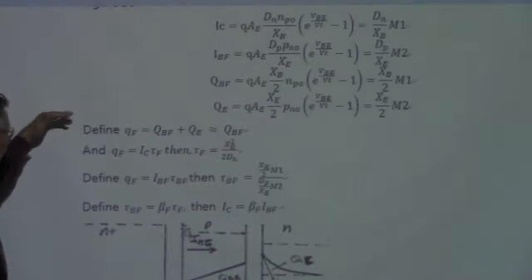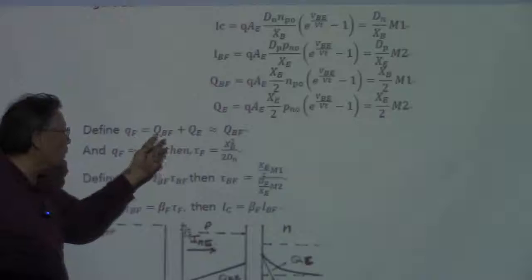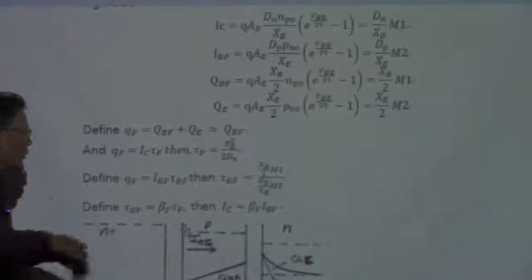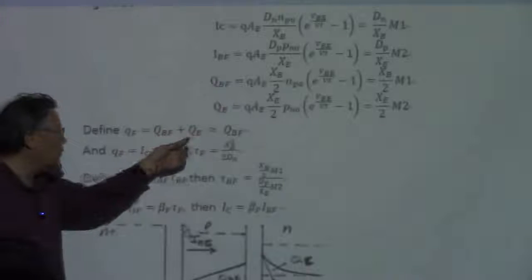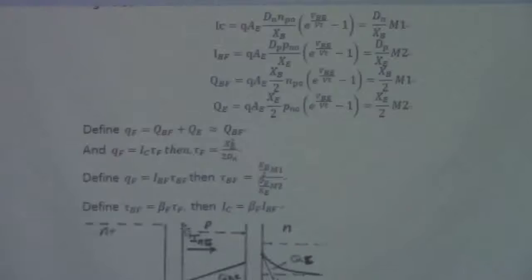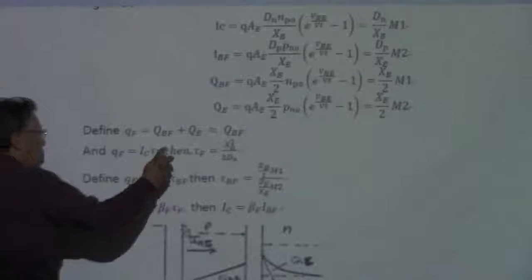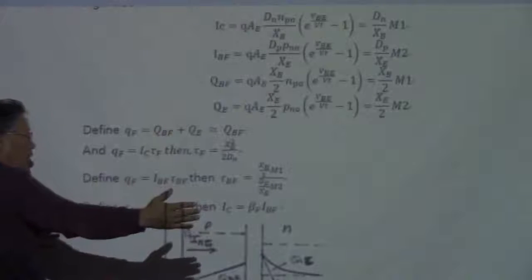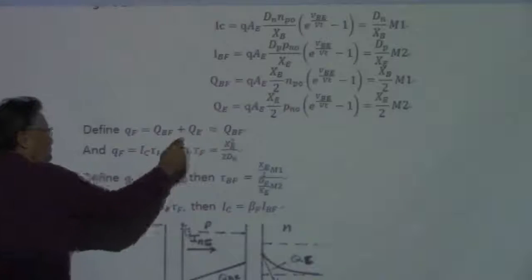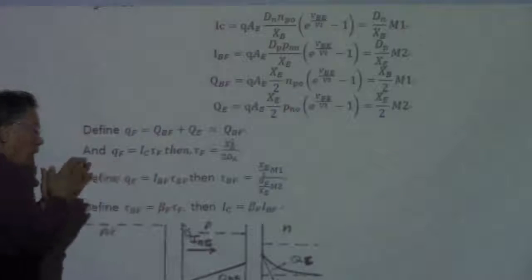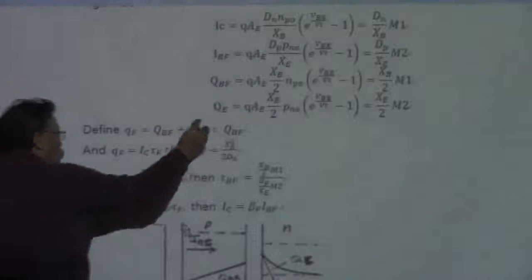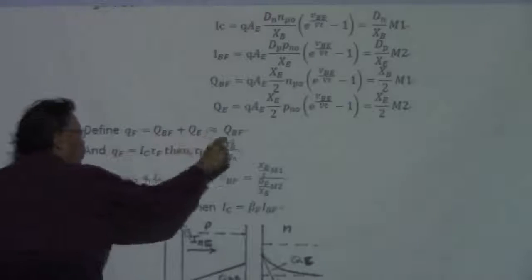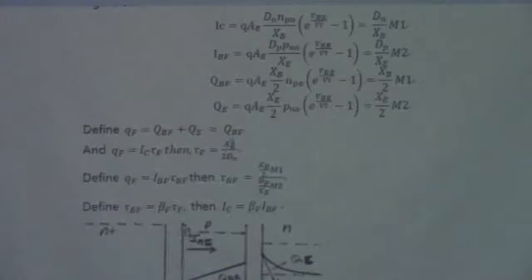And then the important thing is the QF is a summation of these two charges, and then we know the QE is very much smaller than the QBF because of the doping levels. Okay? So we have big charges in the QBF. It's lightly doped and a very big space charge region. And then here on the emitter side, we have a very narrow space charge region, so that the QE is almost trivial. So QF is almost set to the QBF.